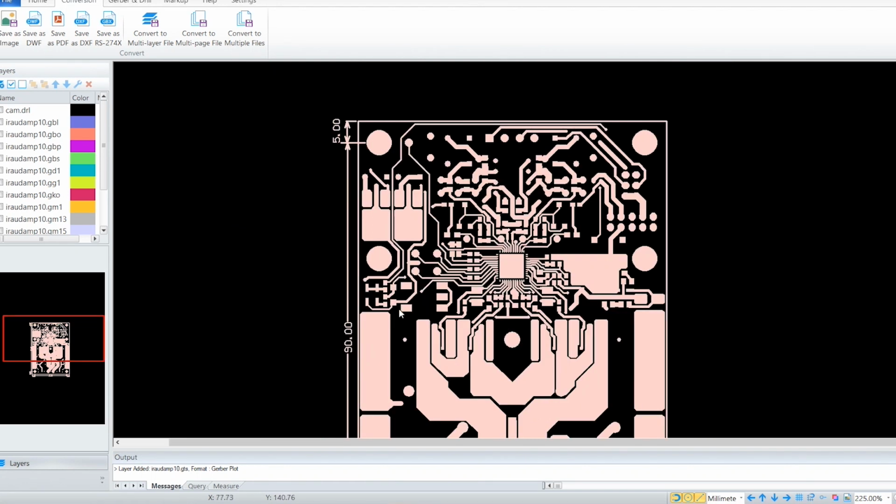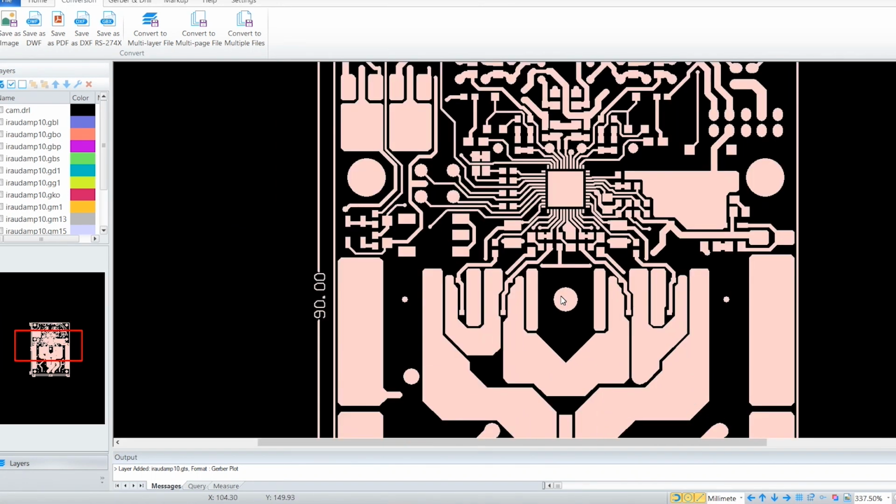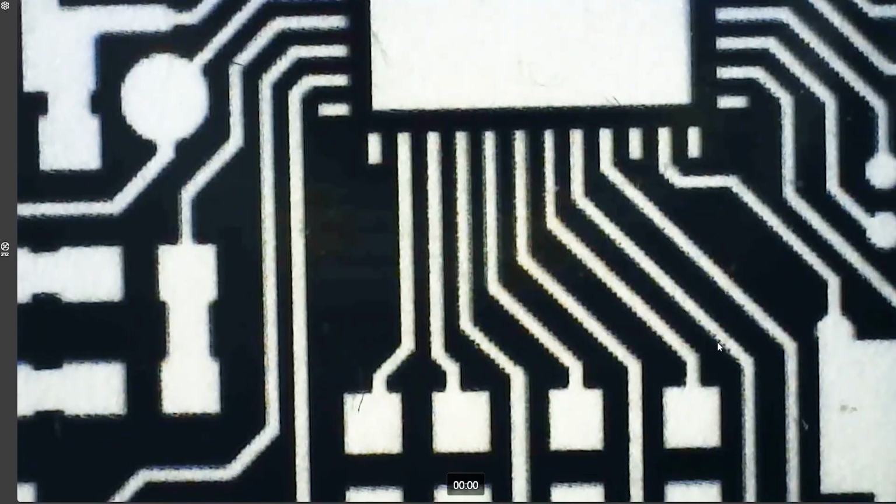And now let's look at several printed artworks under the microscope. How does it look? Here you have a classical example of pixel graphics artifacts. You can see those are 10 mil tracks, and those are already so-so. And due to the artwork, about 20% of area is already jeopardized. Jeopardized. And it is printed by a good printer.